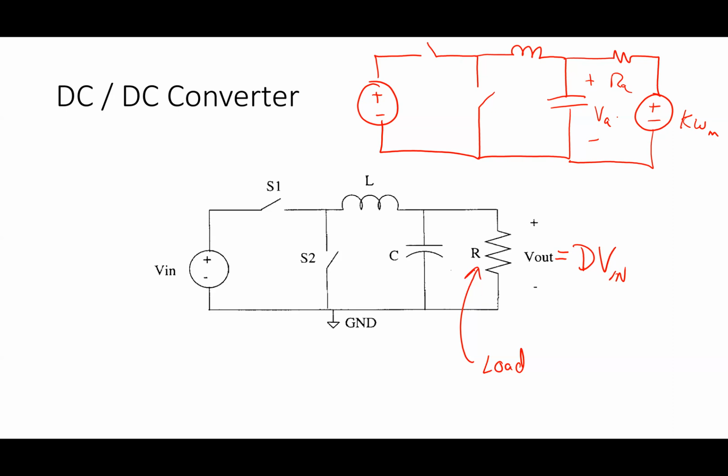You can do some things with that now, but it used to be the case that in a power supply, I gave a 60 hertz input, I put it into a transformer, and then I converted the output of the transformer. So basically the transformer gave me a low 60 hertz. How do I go from 60 hertz to DC? What's the circuit that you would have to build? A rectifier, some diode circuit that would just flatten it out, right? But it'd be a big fat 60 hertz transformer inside there, right?